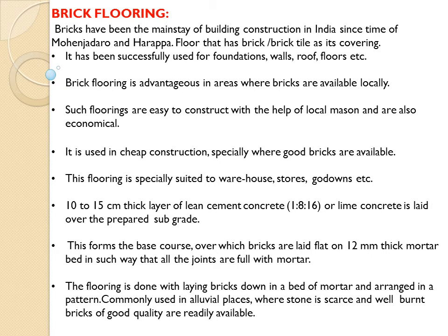So that is the thickness of flooring. This forms the base course over which bricks are laid flat on a 12 mm thick mortar bed in such a way that all the joints are full of mortar. So directly the brick is not placed wherever you need to do a flooring. A proper mortar bed is prepared, then the bricks are overlaid. So the mortar thickness which is overlaid is around 12 mm.